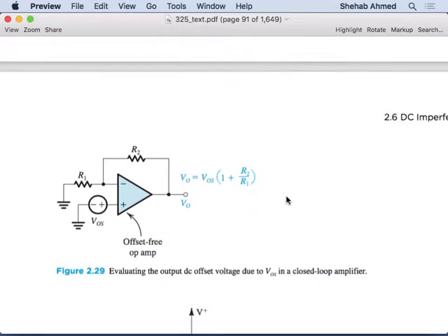If you run it as a comparator and you keep playing with your input signal until the output becomes 0, then you know your offset voltage is so and so, 5 millivolts, right? But an easier way to do it was to run it as an amplifier. Put it in the non-inverting amplifier configuration, but instead of having a source as your signal, remember we can use superposition with our amplifier circuits because they're linear. So build a non-inverting amplifier circuit around it, and don't put an input signal. Just take this signal at terminal 2 and ground it.